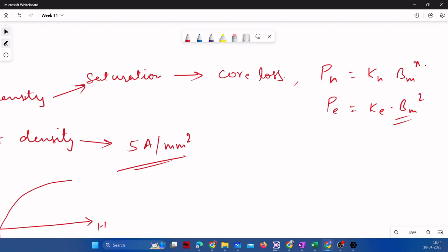Because this ripple current is going to take place and that is superficial, we can wind directly with the bare copper wire, or insulated copper wire, that is easily available. We need not go for Litz wire. Am I correct? At least for an inductor, not for a transformer.